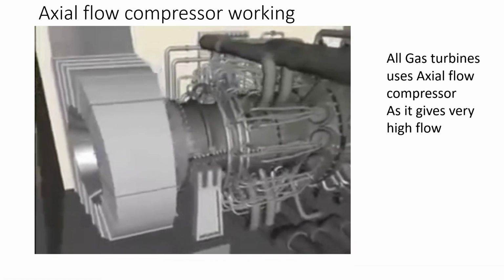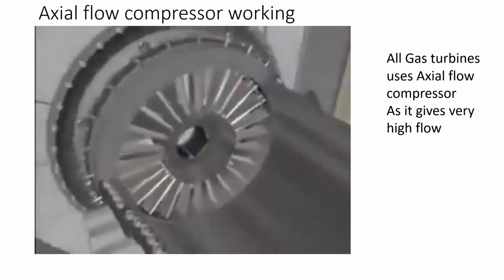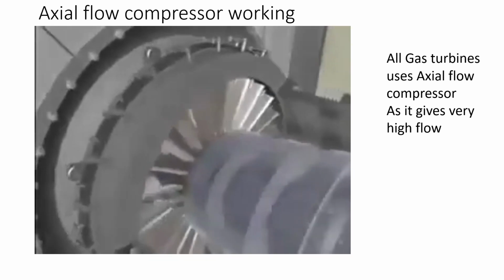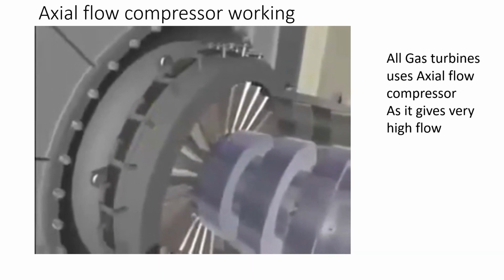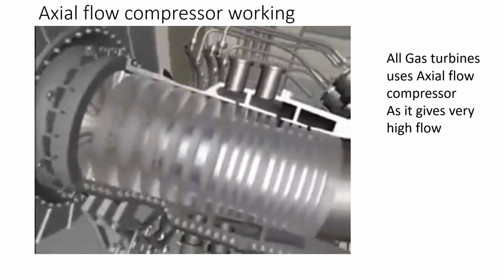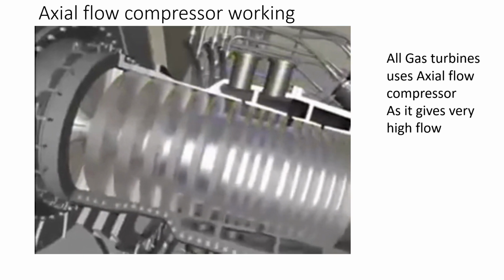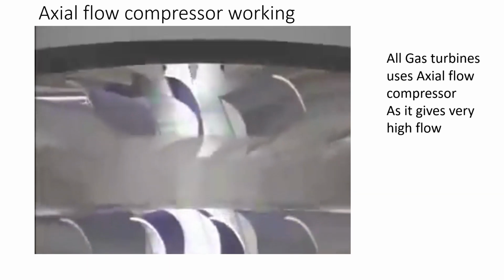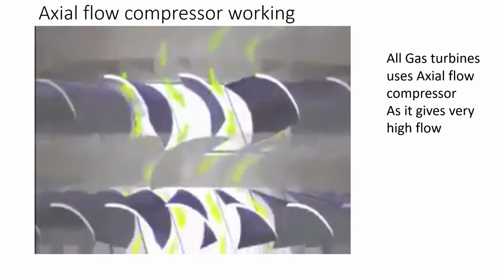Variable inlet guide vanes are located in the inlet casing directly in front of the first row of compressor blades. The vanes are used to regulate the amount of air entering the compressor. The circular operating ring actuates the guide vanes so that all vanes move in unison when opening or closing. Before each set of rotating blades is a set of stationary blades, or blade rings, that direct the air to the next set of rotating blades. The compressor blade rings have stationary airfoil-shaped vanes that direct the air to and from the rotating compressor blades.